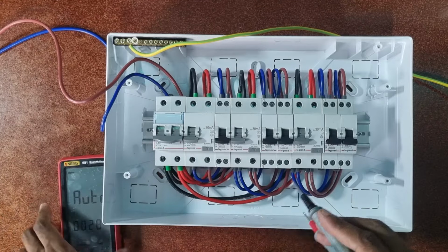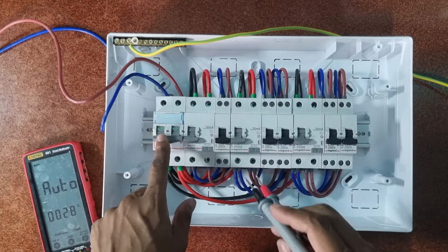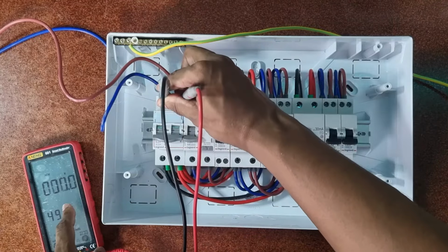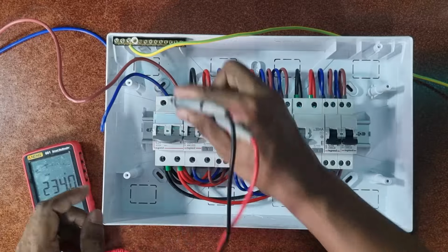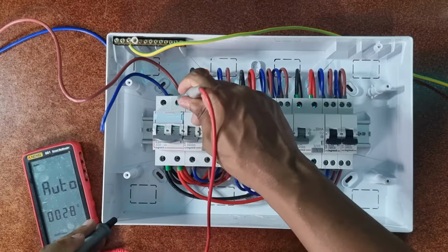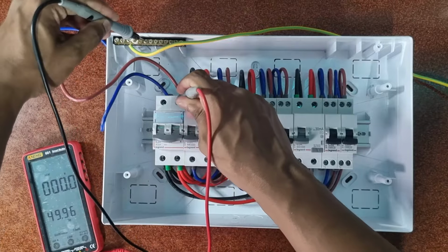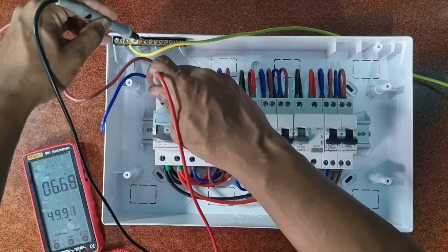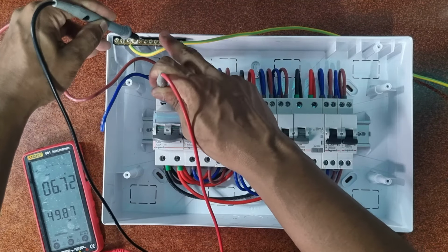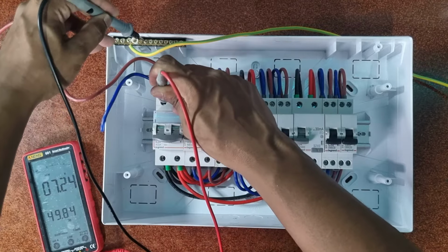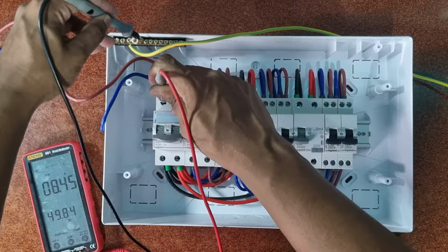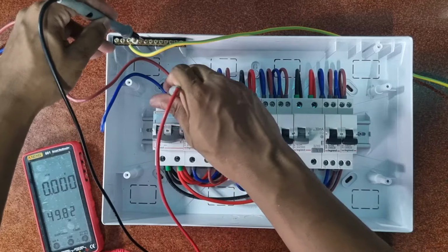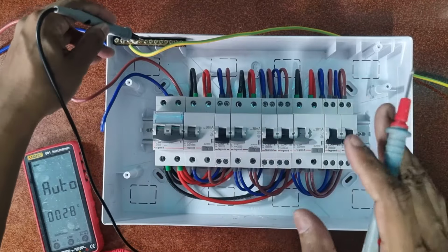So right now, this is my multimeter. I have input here. My input will always be here on the isolator. Let's check for voltage. I have like 234 volt. Now let's check everything is good. Live and ground should be the same voltage. Okay, 229 volt. And now let's go neutral to ground. This is how you check if your ground is good or not. So I have 7 volt through my ground and neutral, 7-8 volt. If it's under 10 volt, it's good. If it's above 10 volt, that means there is some fault, some problem in your appliance.